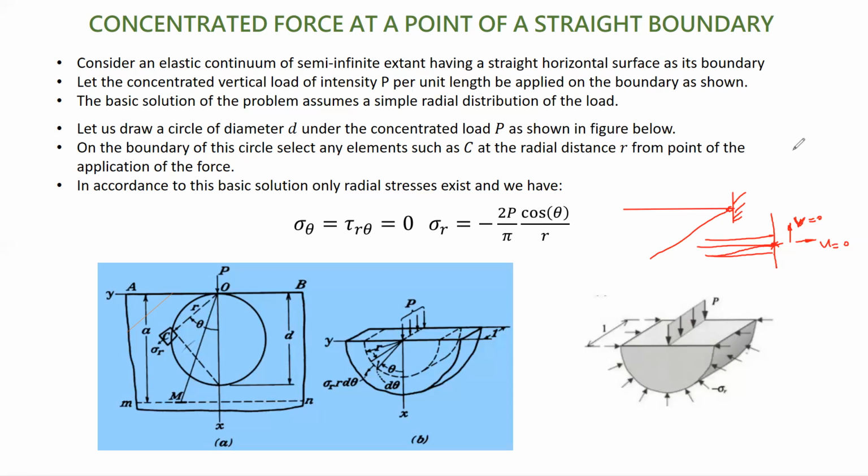But in reality, I can make the slope in this plane equal to 0, or the slope at this end is equal to 0. The vertical or the horizontal. Derivative of v with respect to x is equal to 0, or u with respect to y. So both of them are feasible assumptions, and we arrive at two different solutions. So we have to satisfy these boundary conditions.